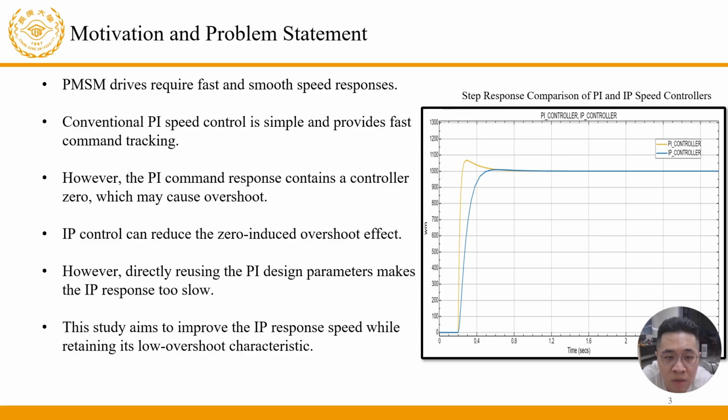its low overshoot behavior. This figure on this side shows this basic difference. The PI response is faster, but it has overshoot. The IP response is smoother but slower.